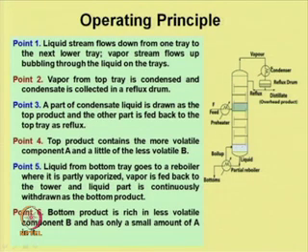So, this is the diagram of a typical distillation fractionator, where the liquid stream flows downwards from the top of the tower from one tray to the other, and the vapor flows from bottom to top, bubbling through the liquid.